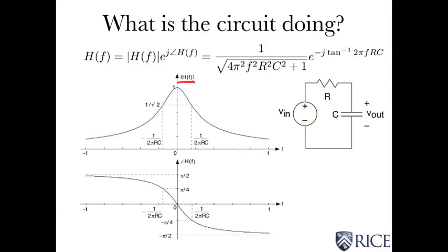There's the magnitude, there's the angle, so you can compare what's happening to the phase and the magnitude at some given frequency. Okay, so let's look at this. The general rule of exploring these transfer functions is to look at what happens at very low frequencies as f is going to 0, and at very high frequencies as f is going to infinity.